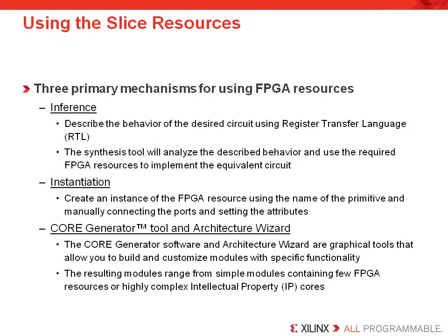There are 3 ways to get the FPGA resources you need into your design. You can either infer logic with your synthesis tool, instantiate primitives from the Xilinx Unified Library, or instantiate an optimized component from the core generator. One of the biggest challenges for new users is to make certain that they are inferring the appropriate resources. First of all, one of the best ways to check that you are getting the resources inferred is to check the schematic viewer from your synthesis tool.